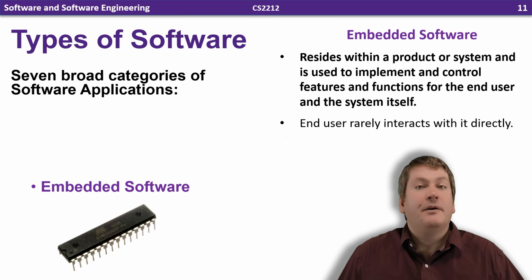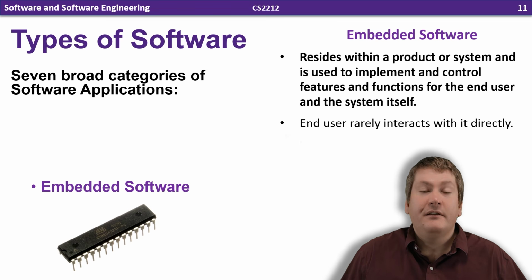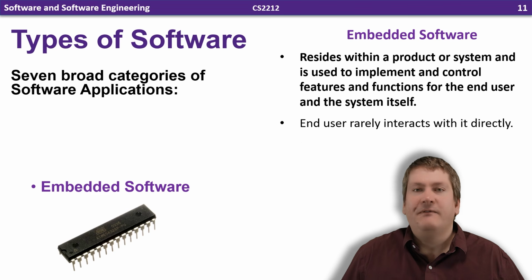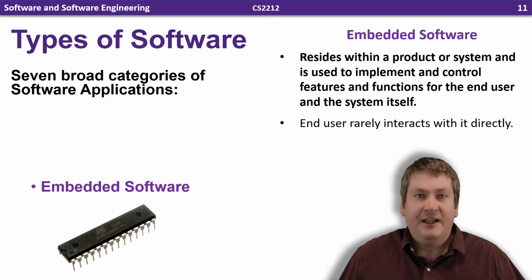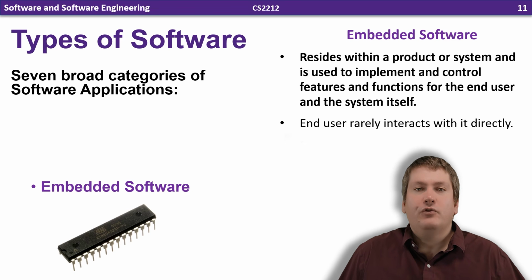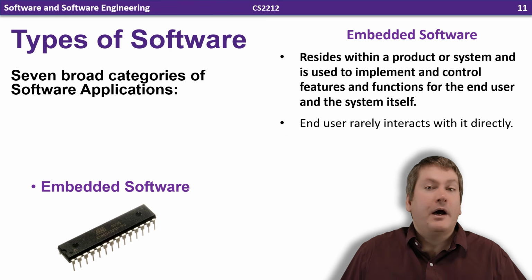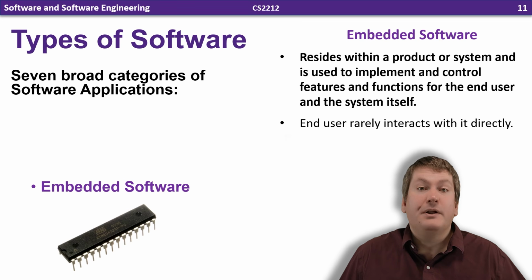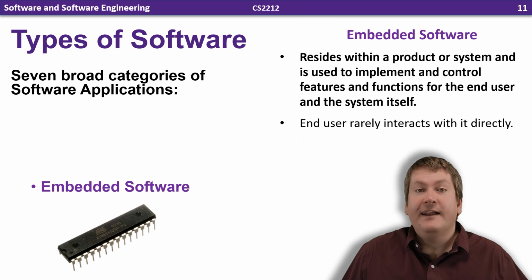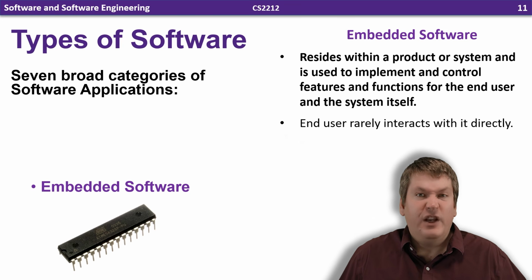This is a fairly common microcontroller used by hobbyists and for prototyping, and it can be found in things like Arduino development kits. These microcontrollers are programmed directly, typically using something like assembly, C or C++, and unlike a modern desktop operating system, they typically run one program at a time that controls hardware by taking and giving output from the pins of the chip.